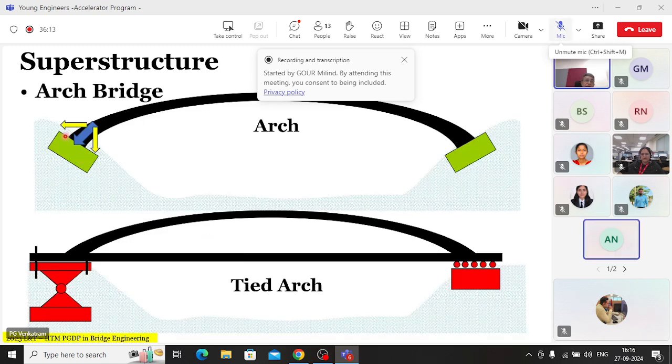Right. So it needs to be very strong, anchored into the... What do you mean by anchored? Let us say that I have a clay here and I put an anchoring into the soil. Is that good enough? No, sir. So anchor is not the answer. So what is the answer? The answer must be in the shear strength of the soil itself. It must be very strong to take care of this horizontal force.